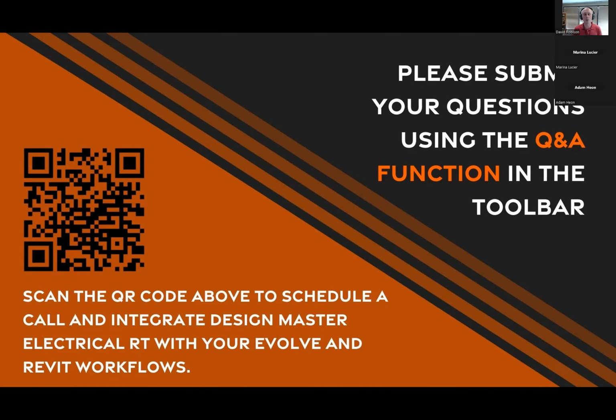They haven't been inserted on the one line. It'll do a first pass of where they belong. They're never going to be exactly how you would draft it if you were doing it manually. You can go back and adjust it, but it gets everything in there, and then you can start working from here. So it'll lay out those panels, get the feeders inserted. So it'll build out that portion. So that's if you have the stuff in Revit already. You can have it generated. You can also place it one piece at a time.